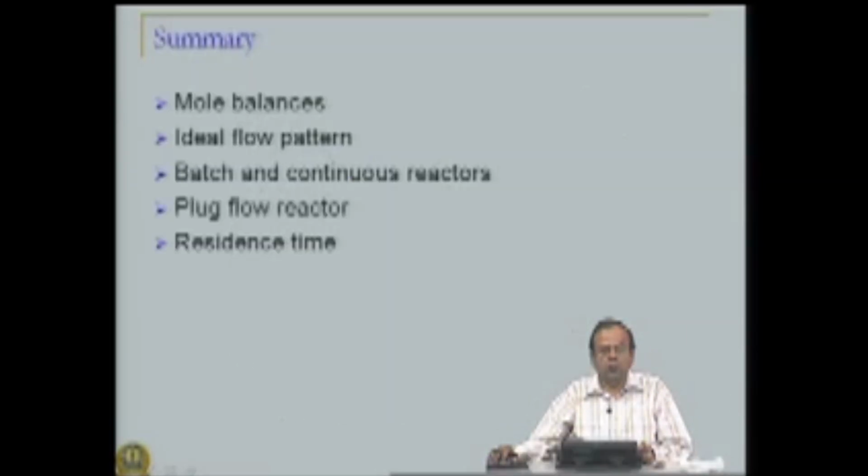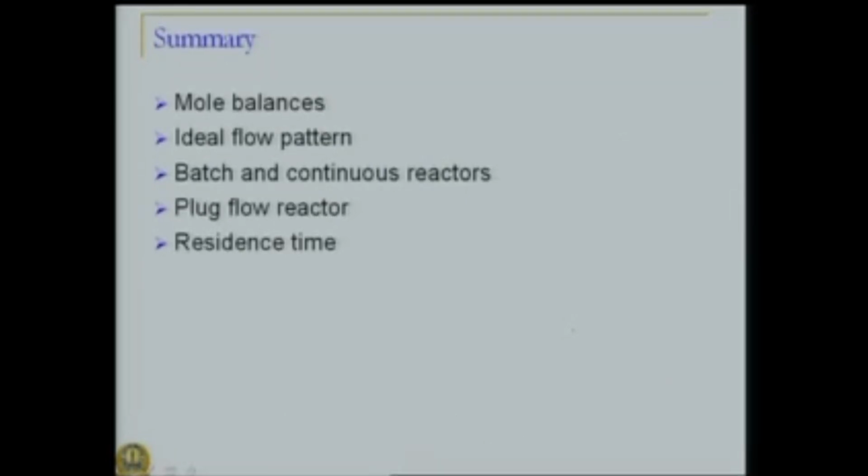With this, we will come to the conclusion of our design equations. Essentially, what we saw in this lecture was how to do a mole balance on a reactor, and we considered only ideal reactors. Ideality depends on the flow pattern inside the reactor, that is, whether it is a well mixed reactor or whether there is no mixing in the axial direction, a plug flow reactor. We have different kinds of reactor behaviors. We also have different types of reactor operations, batch and continuous.